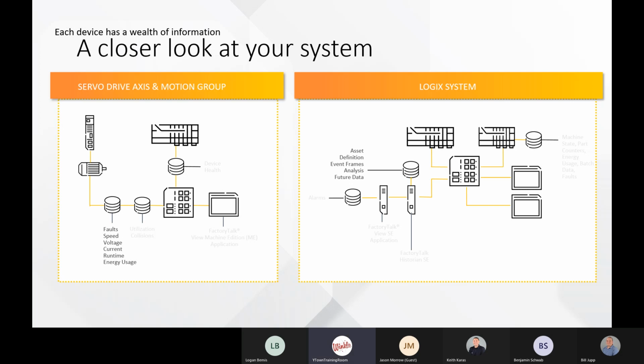I guess we can talk about how Cisco switches provide system health of a network: network utilization and switch health, going back to the connect phase. An increase in network activity is a red flag that you may have a defective network device or an unwanted device accessing your network. So this goes back to security and the connect phase. If you're familiar with the Rockwell platform, the Logix platform provides module diagnostics, but it's typically only viewed when there's a problem. What if the system could alert users when operating parameters are trending toward a hardware failure? Again, back to the predictive mindset.